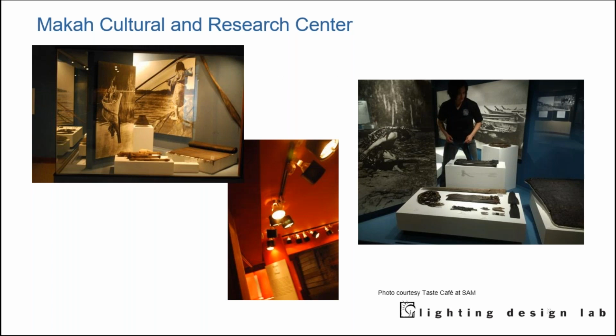The conservator was brought in, and we discussed effective light color, light output, wattage, maximum lumen hours allowed on the artifacts, and if we could increase the light level, because the new control system now allowed each case to be controlled by external occupancy sensors that illuminated the space as you entered the gallery, turning it off behind you when you left. That allows us to increase the amount of annual allowed light on the artifacts while staying well under the conservator's requirements.